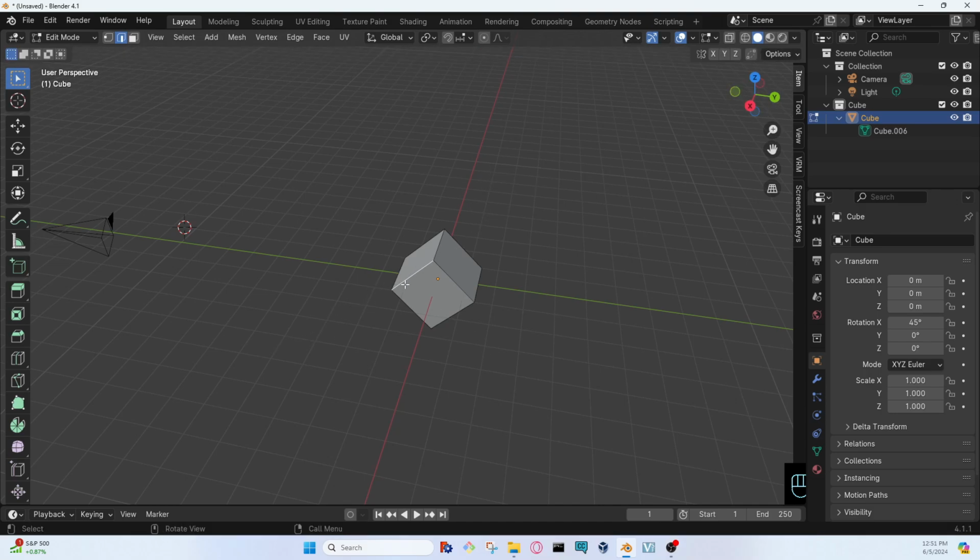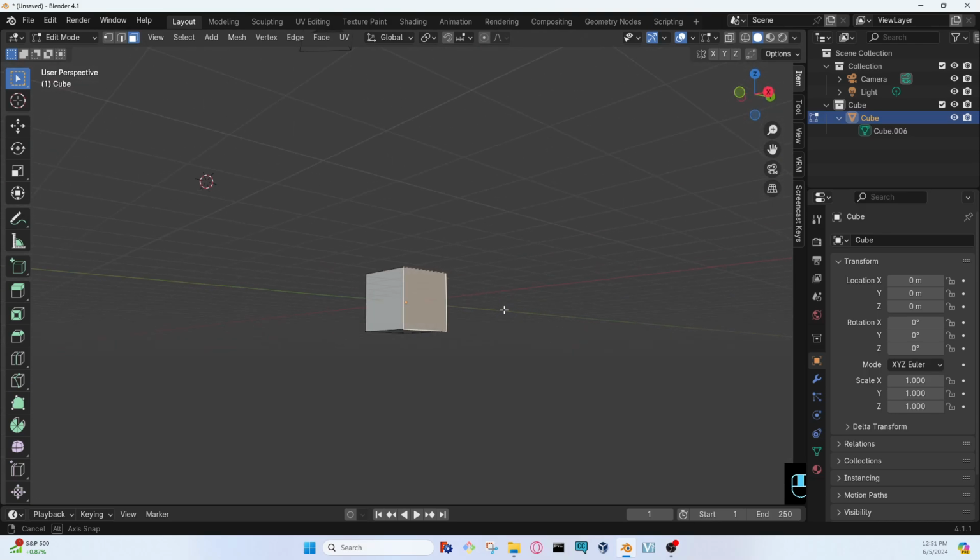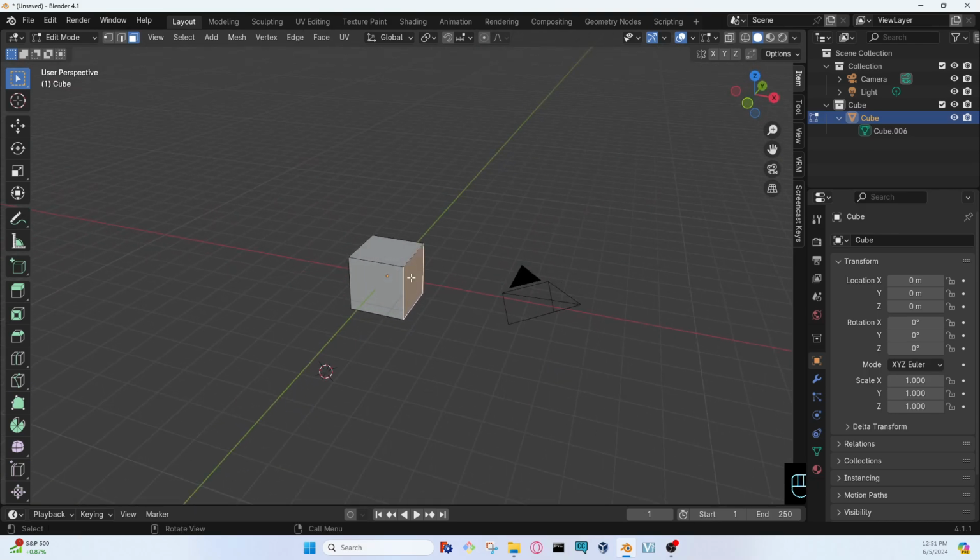There will be some math involved when you rotate objects. So normally when you scale things, you want to be across the 3 planes, in some way, shape, or form being on the 3 planes, and then scale it. Then go ahead and do your rotation. That way it's much easier to work with. So we're going to put him back to 0. We're going to go to faces. We're going to scale faces. Now, because you are scaling a whole face, you are grabbing 4 individual lines.